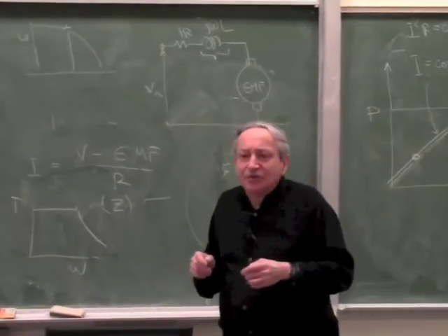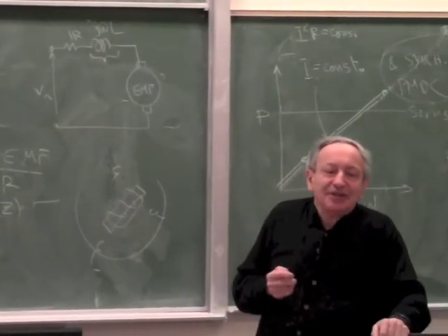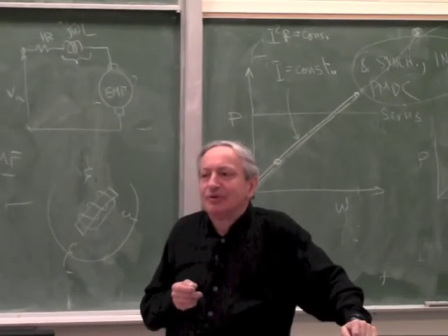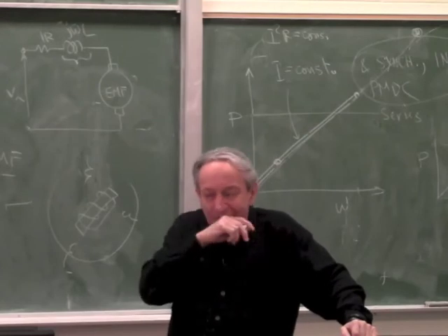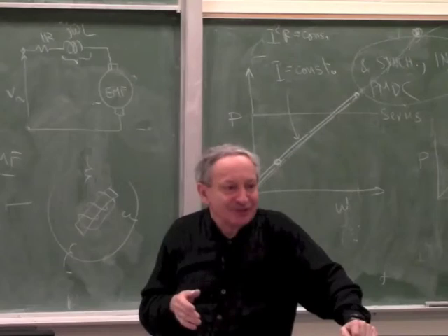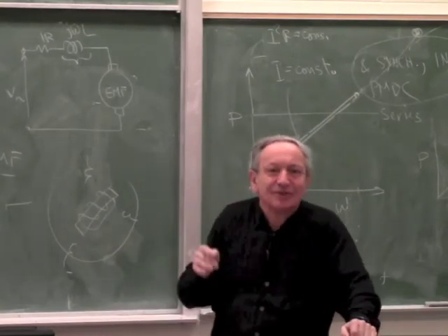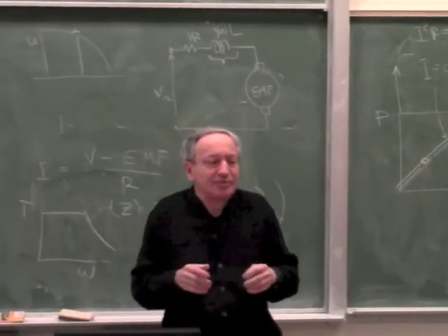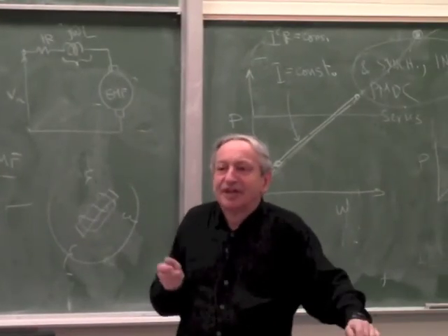So you do gain power, because typically if you really want to make a motor to run at a low voltage and efficiently, you have to make it with many poles, because otherwise you end up with a very low frequency. Okay, so if you make it with many poles, it has many windings, it becomes bulkier. So if you really want a very high performance motor in terms of horsepower, you are better off making it small and very high RPM.